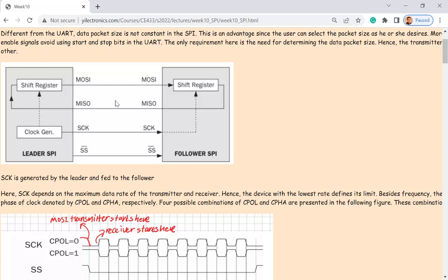So if you have an SPI module on that CPU or the SoC, system on chip, you can definitely use it for this purpose. But do we have an SPI module in our FPGA chip? On the Basys 3 board, do we have an SPI over there? No, it's blank. It's just all these individual gates, or lookup tables.